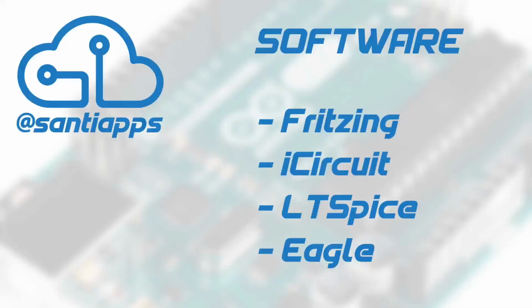Okay guys, so in this episode we're going to check out some of the more popular software packages that we can use in our electronic projects. We are going to specifically look at four software. The first one is Fritzing, which is more used for designing circuits and wiring stuff up. iCircuit is actually a Mac application which is used for visualizing operational circuits. So you're able to see what's going on, current flow and voltages and whatnot. And LT-Spice is very similar, but it's much more complex, as you will see, than iCircuit. And it can be used to design circuits and, of course, also see their operation.